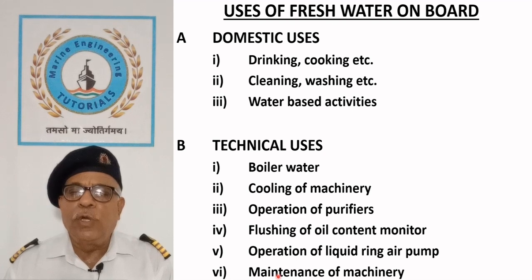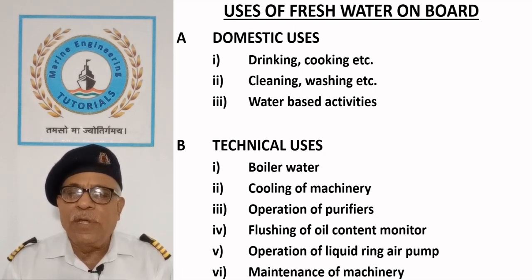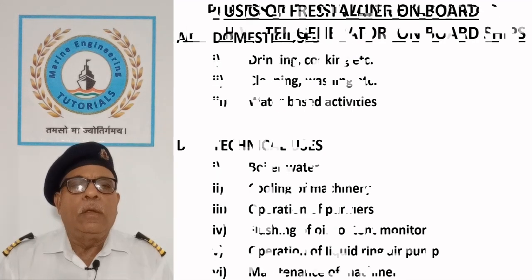Freshwater is used for maintenance of machinery such as washing turbochargers, compressor and turbine sides during the service, impeller of inert gas fan after stopping, water washing of boiler tubes, chemical cleaning of freshwater generator or scavenge cooler, rinsing cooler tubes or plates, etc.